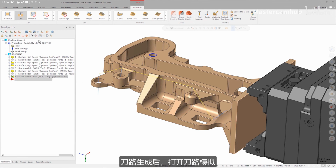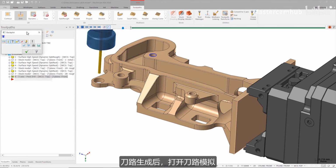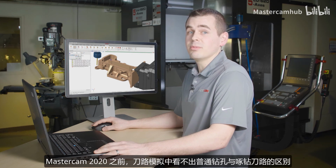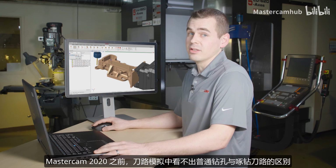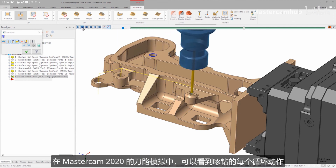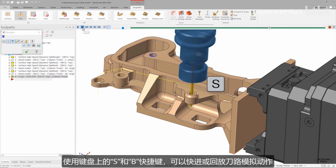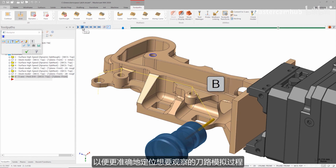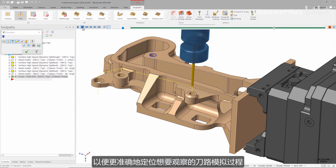When the toolpath is done generating, I can launch Backplot. Prior to Mastercam 2020, there was no visible difference between a standard drilling operation and a peck drilling operation when you reviewed them in Backplot. Starting in Mastercam 2020, each peck of the drilling cycle is now simulated. By pressing the S and B keys on my keyboard, I can step forwards and backwards through Backplot, allowing me to take a closer look at individual moves or motions.